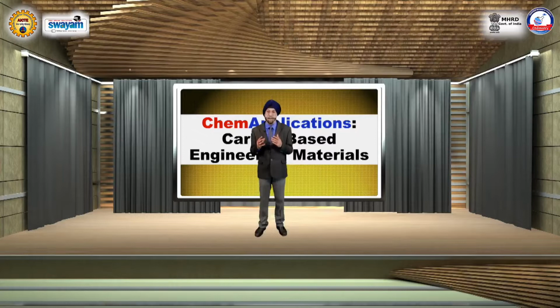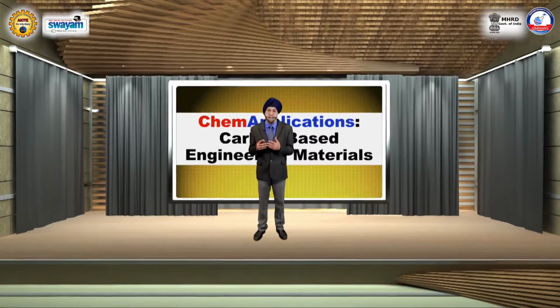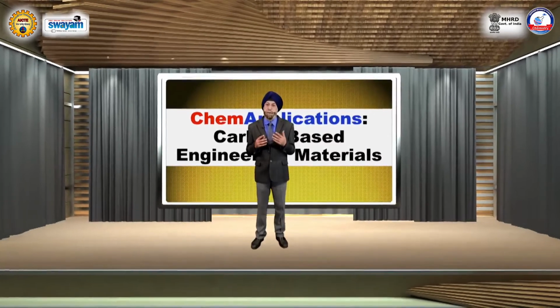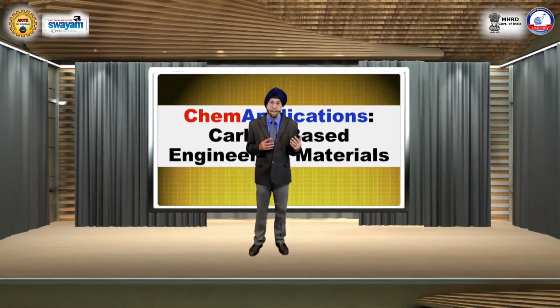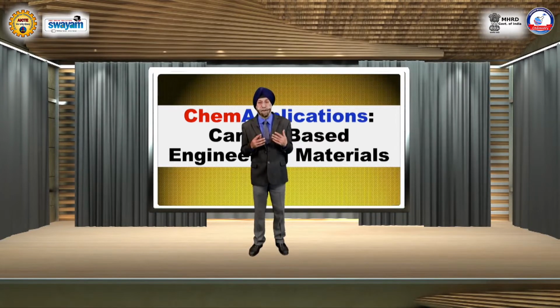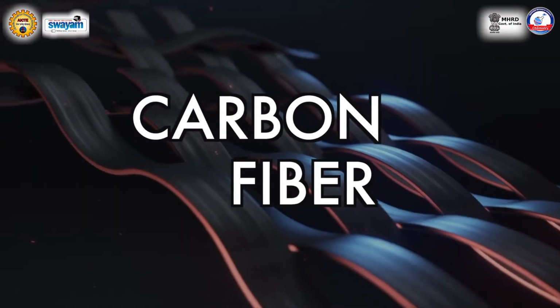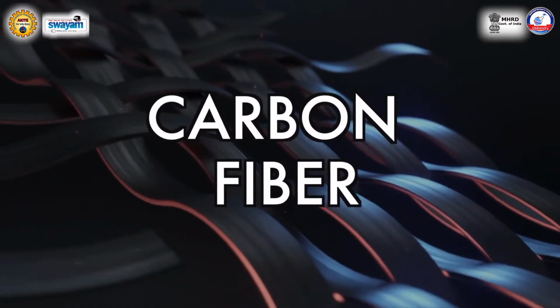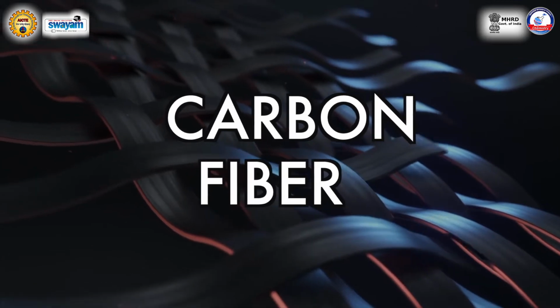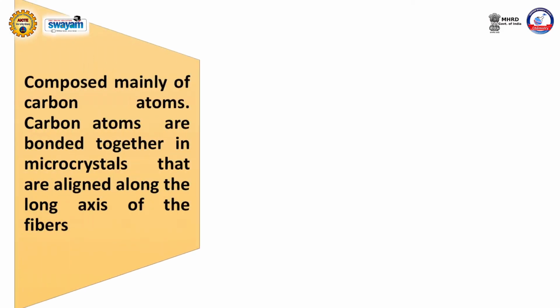Dear friends, today we discuss two commercially important materials, carbon fibers and carbon steels. The common thread in these two broad categories of workpieces is the role that carbon plays in imparting engineering characteristics to these materials. A carbon fiber is a long, thin strand having a diameter of 5 to 10 micrometers and composed mainly of carbon atoms.